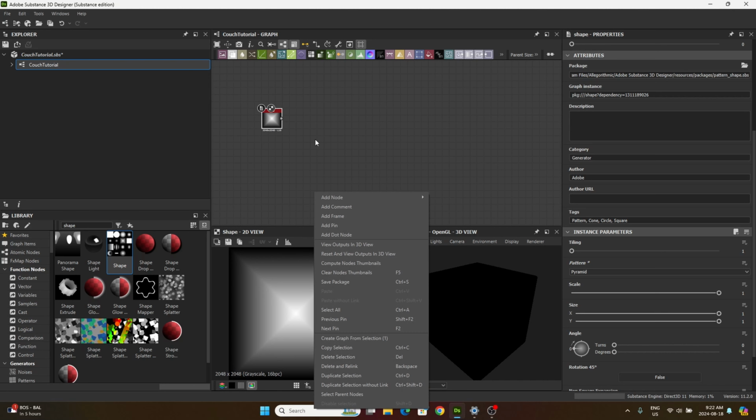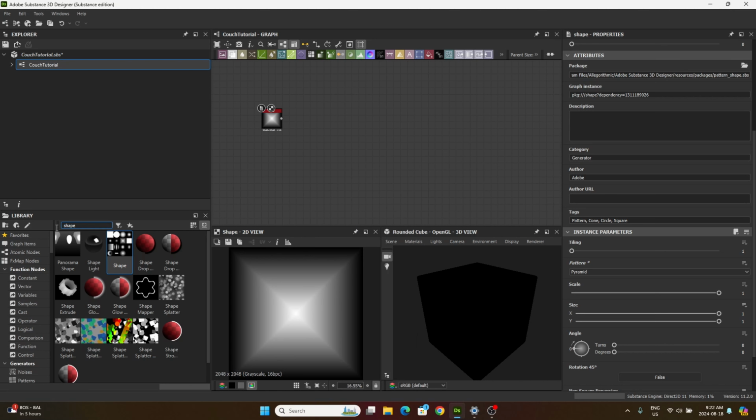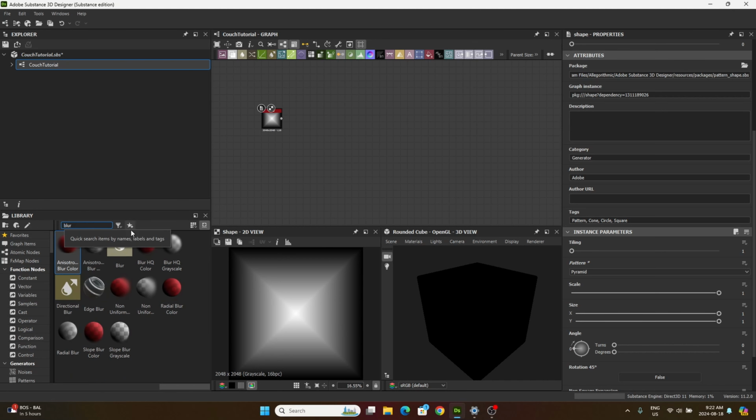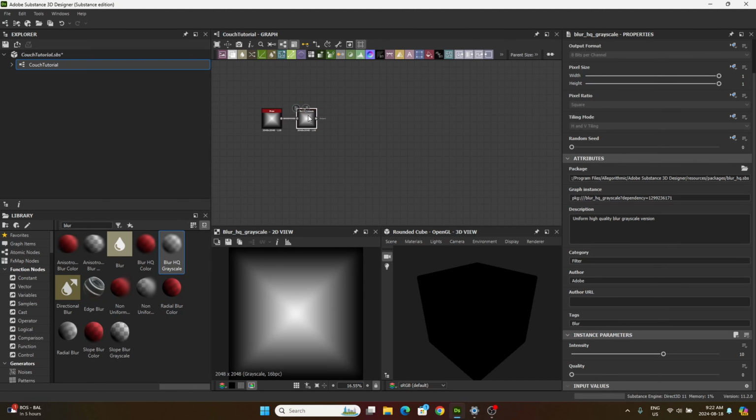Okay, so next we're going to do a blur HQ grayscale. Here we go, and just attach that in there, and then we're going to set the intensity to 16. Just crank that up, and then we're going to crank the quality up to 1 as well.